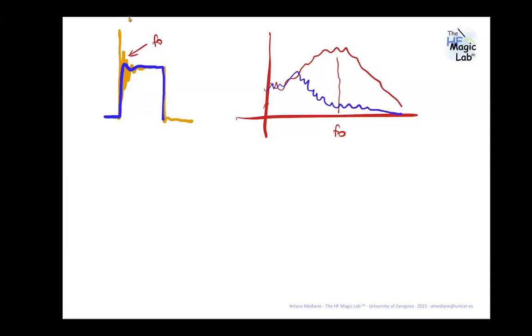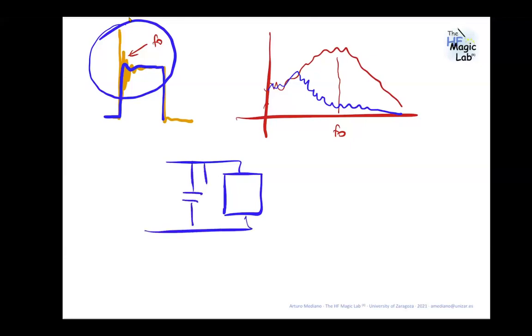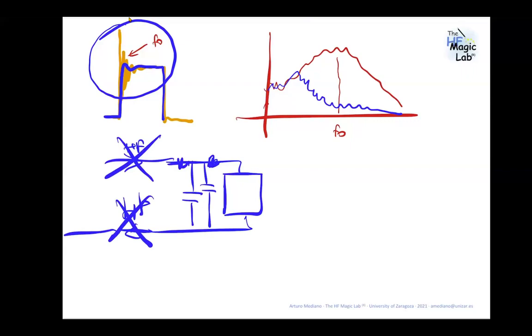So why is this killing the source? I am killing the source because the energy that was created and radiated is not necessary in my circuit, and I make it disappear. You have other possibilities. For example, if you have a circuit that is not very well decoupled, you can introduce a good decoupling circuit, depending on the application, to minimize the possibility of high frequency current in the power lines. High frequency is not permitted in the VCC or the ground lines. You can try to work inside the circuit to avoid this energy.